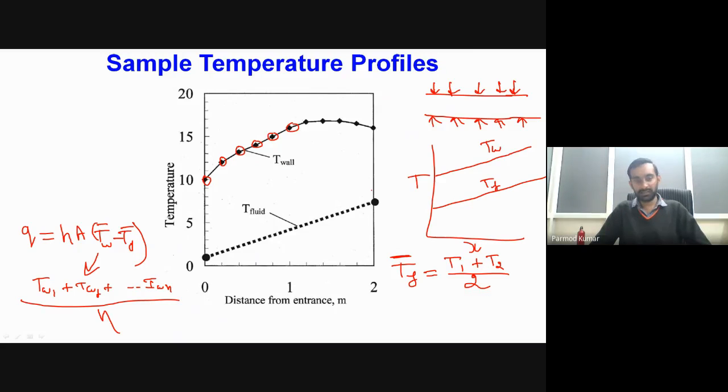will be giving us an idea of what type of instrument we should select. Okay, and how much uncertainty we will be getting in our final output. So uncertainty analysis has to be done prior to the selection of the instrument. Okay, because first we will be taking one type of instrument. If it is giving very high uncertainty in our final measurement, then obviously we will be selecting some precise instrument of low uncertainty. Okay, so uncertainty analysis has to be done prior.